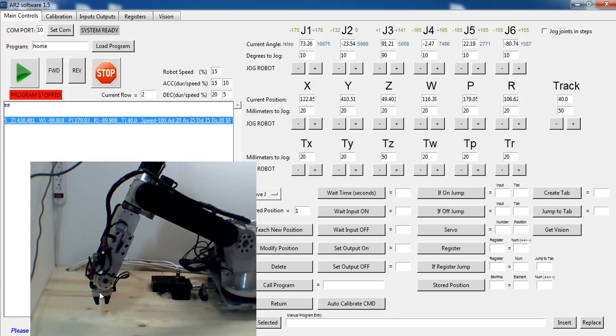Robots have a few of these singularities. The biggest one, the one that's a pain in the butt, is the wrist. The other one is the elbow, because the elbow back configuration means you can get to the same spot in 2 ways. I chose to not deal with elbow back. As you can see up here, for J3 I've limited joint 3 to go from 1 degree to 141 degrees. I've never had a need in all my years of programming robots to flip the elbow backward. It looks cool when robots can flip all around, but mathematically it just added a bunch of work that I didn't want to do, and I'm lazy. So the only configuration I'm dealing with is the wrist.